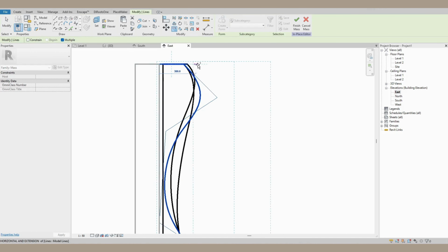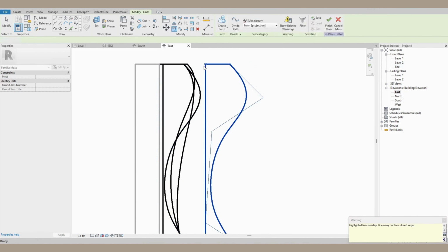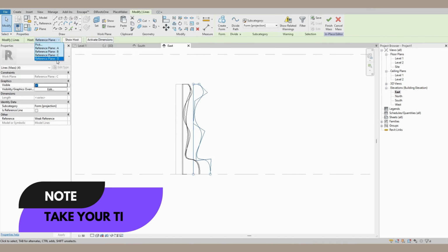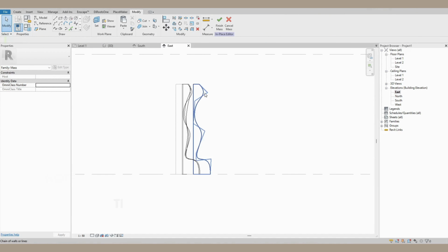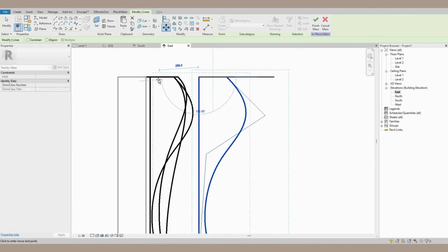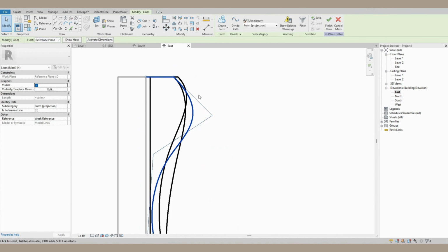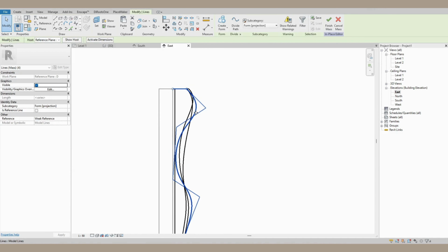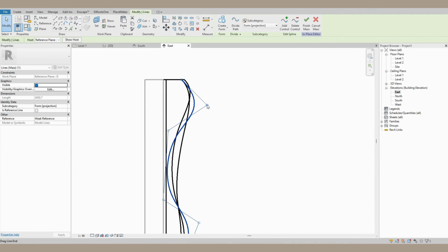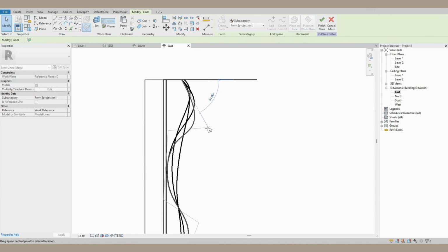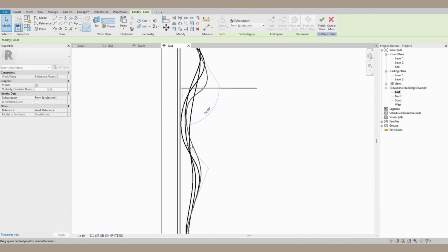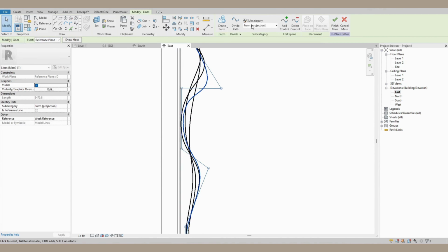Make sure to always use the CO tool, which is copy. Always use the MV tool, which is move. We don't move things loosely in Revit because that might create inaccuracies. Great. And this allows you to just move your spline tool. I really love it. You can add or remove points really to get the shape that you want. I feel like in interiors, it's very crucial to get those little millimeters that you want of the backrest or of the seat. It's really helpful.